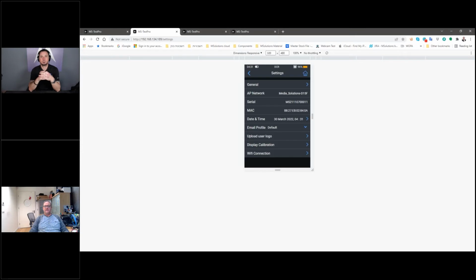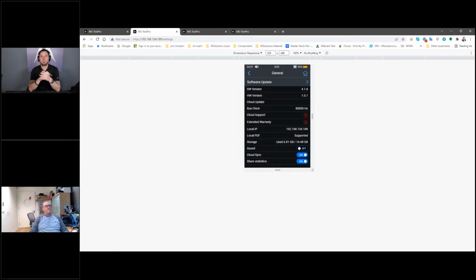The moment that you plug in the tester to the network from the RJ45 connector next to the 4 USB inputs of the main unit of the tester, you will get the local IP information, how to log into the tester. Now, if you connect the tester to the Wi-Fi environment, you will get it also here. It will be written with a small w at the beginning. It means Wi-Fi and the IP. You can access it directly from your system, from your laptop, PC, or everywhere on your local network that you are connected to.